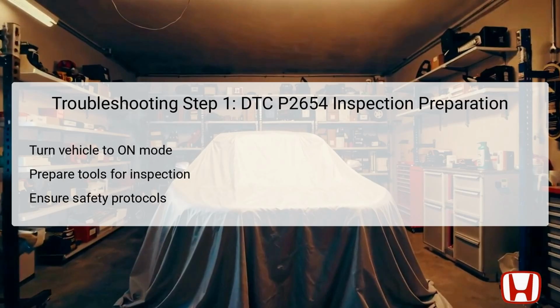As the first step in troubleshooting DTC P2654, the vehicle must be set to the on mode to power the electronic systems, enabling diagnostic capabilities. Proper preparation entails gathering the necessary tools for inspection, which may include multimeters and a Honda Diagnostic System (HDS).